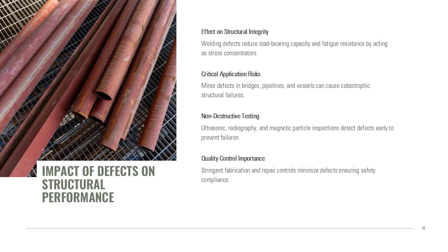Regular inspection using non-destructive testing methods like ultrasonic testing, radiography, and magnetic particle inspection is vital to detect defects early. Implementing stringent quality control during fabrication and repair minimizes defect occurrence and ensures compliance with safety standards.